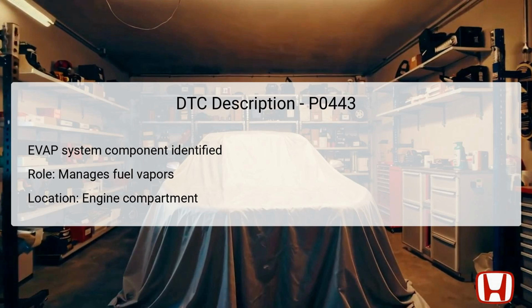The main function of the EVAP canister purge valve is to control the release of fuel vapors that are captured in the EVAP canister. These vapors are routed to the engine intake under controlled conditions, allowing for complete combustion and minimizing emissions. The purge valve typically resides in the engine compartment, connected to various hoses and electrical connectors. When this valve fails to open or close correctly, due to electrical faults or mechanical blockages, it can lead to increases in emissions and trigger a check engine light.